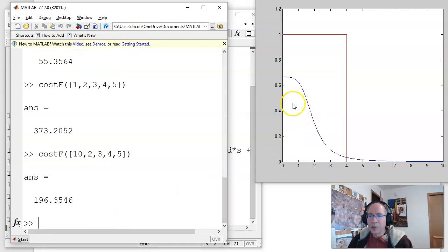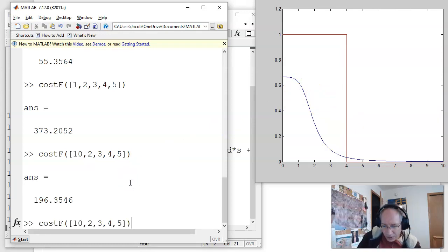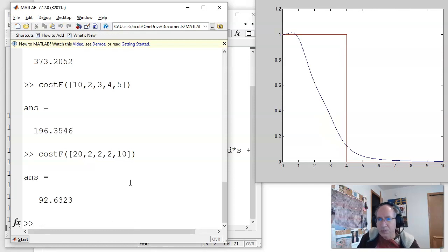I probably want a pole right around -1 plus j1, another pole at -1 plus j3. So that would be -1 plus j1 would be s squared plus 2s plus 2. -1 plus j3 would be s squared plus 2s plus 10. And the numerator should be 20 for DC gain of 1.